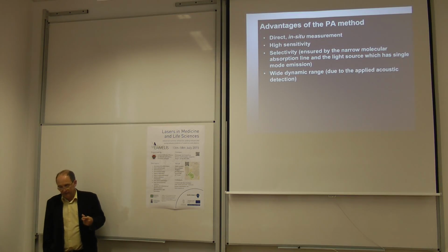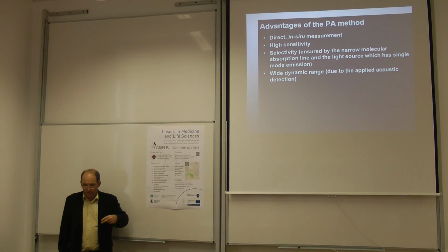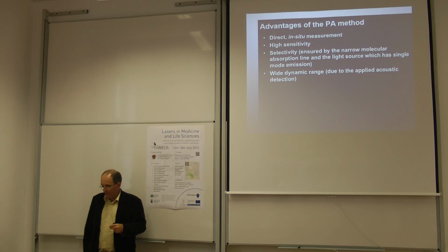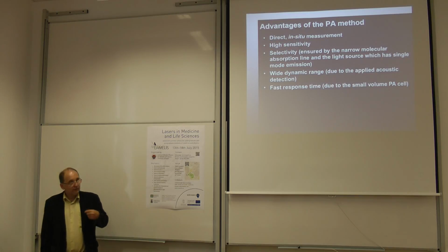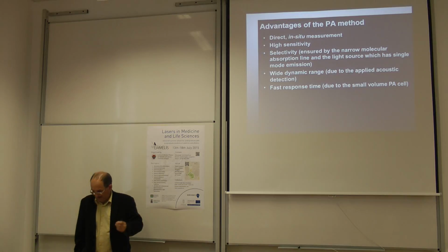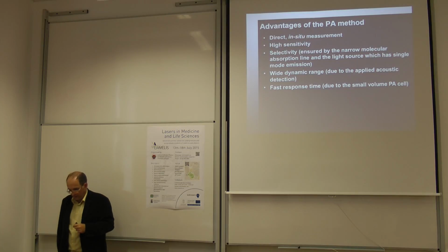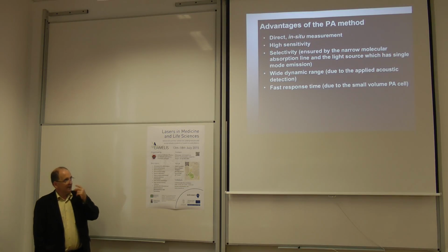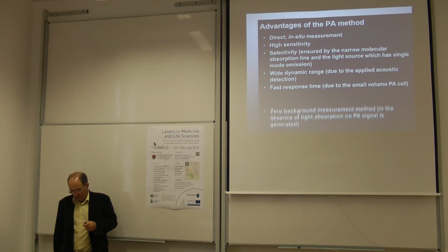The photoacoustic method also has a wide dynamic range because of the applied acoustic detection: 5 or 6 orders of magnitude of concentration variation can be detected. It's also a fast response system because the volume of the photoacoustic cell is small and you have a continuous gas flow. That means that if the concentration is changing, your system responds fast, with a response time in the range of 1 or 2 seconds.